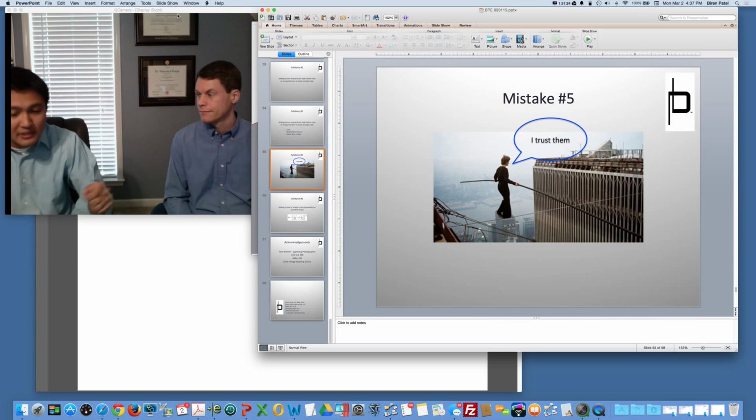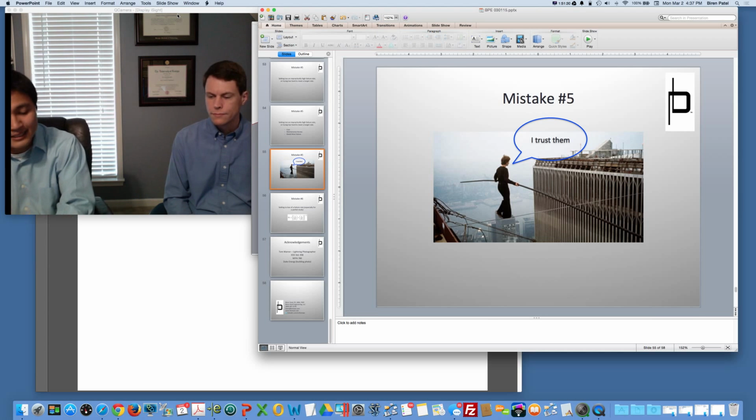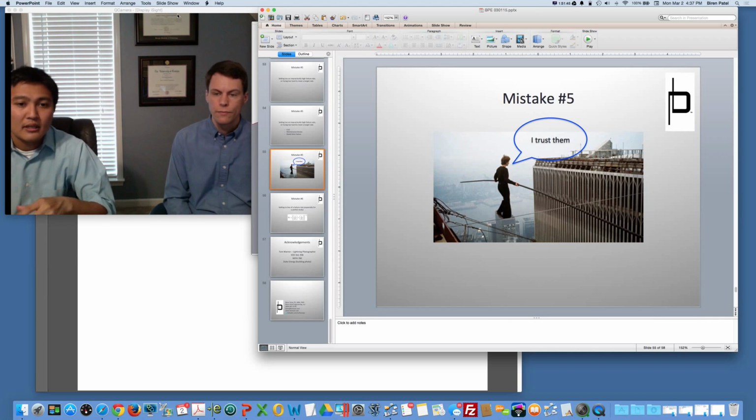They won't always. There's tension and they could snap and move a little bit, but hopefully they'll fall, generally speaking, downward and not land on bus or something like that. Whereas others say, go nuts. You put as many shield wires as you want. We don't have a problem with shield wires falling, and we care more about saving the money. So it's something to think about with your client and the environmental factors.